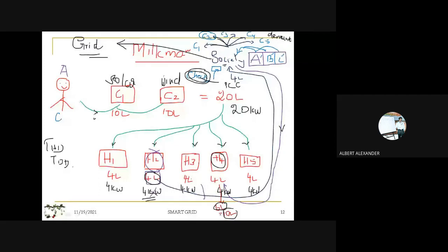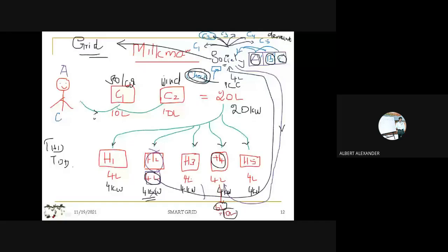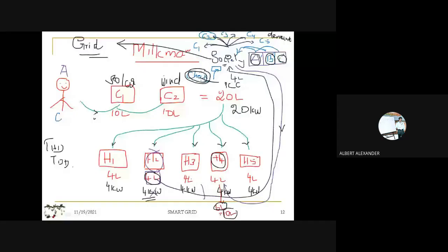But the checking point is available only at the society, because like this milkman or this microgrid, some other power generating stations will also come, in different villages. When all the people are giving the power at the same point, that point is called the grid. So a grid is a point where all the generating stations meet. At this meeting point, before I deliver the power to the grid, I want to check the power. That checkpoint is called the point of common coupling. So normally we have to measure the THD only at the point of common coupling.